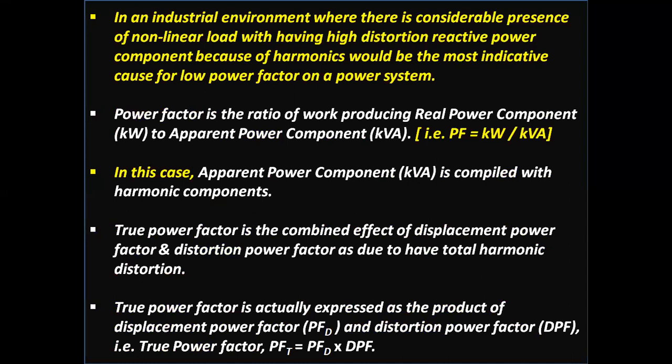True power factor is the combined effect of displacement power factor and distortion power factor, due to total harmonic distortion. True power factor is expressed as the product of displacement power factor, that is PFD, and distortion power factor, DPF, that is true power factor PFT equals PFD into DPF.